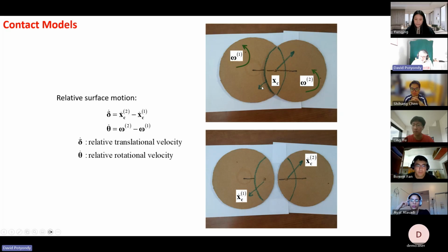So the contact force is equal and opposite. This guy is going to say, I have a contact force at this location pushing me in that direction. And conversely, I'm over here. And so when I sum up the total force and when I sum up the total moment about my center, it's actually acting here, okay? And so this is one of the details of how we're handling the overlap. There's always a volume of overlap, and in the center of that is where the contact is.